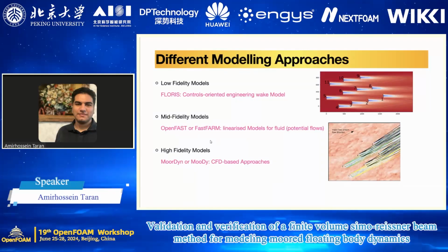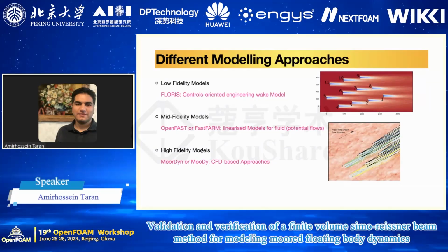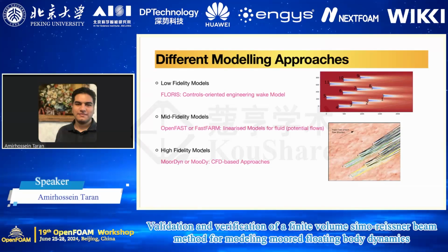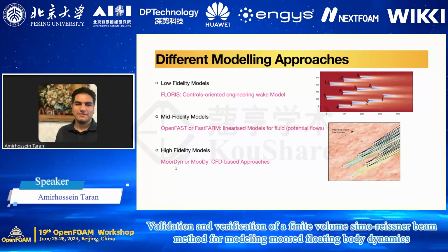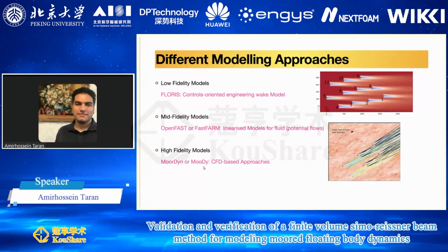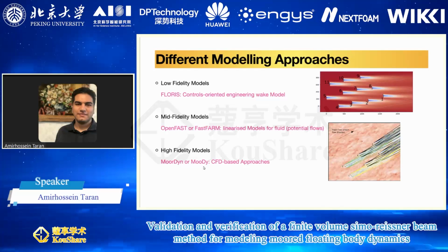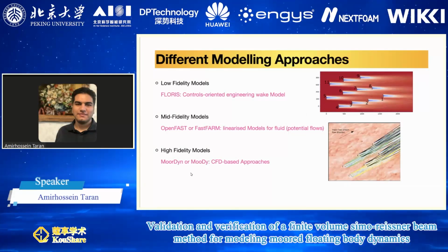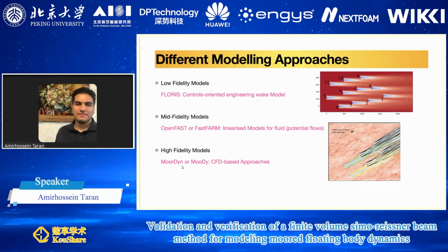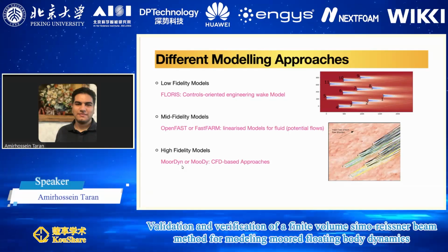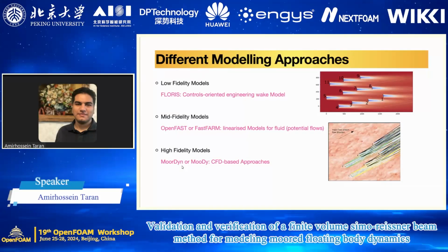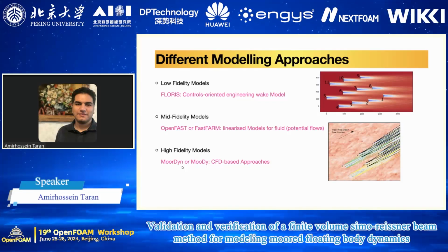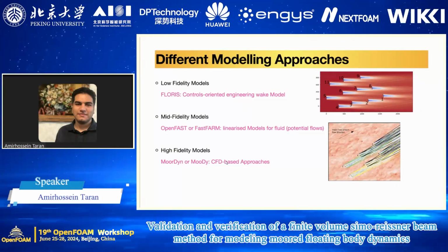And more recently, high fidelity models have a separate mooring line model connected with a CFD-based approach. For example, MoorDyn and MOODY are two famous mooring line simulators, where MOODY is based on finite element and MoorDyn is based on a lumped mass approach, which I'm going to talk about in the next slide. They connect their mooring line approach with the CFD approach. So in terms of the fluid and the forces coming from the fluid, it's a high fidelity approach.